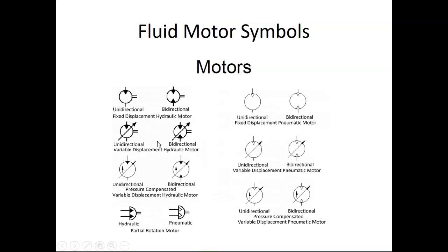You have ones that are pressure compensated. By the way, what does it mean to be hydraulic versus pneumatic? You have the colored in triangle versus the clear triangle. Clear is pneumatic, colored is hydraulic. Clear is being air, and if you've ever seen hydraulic fluid, it's not clear.